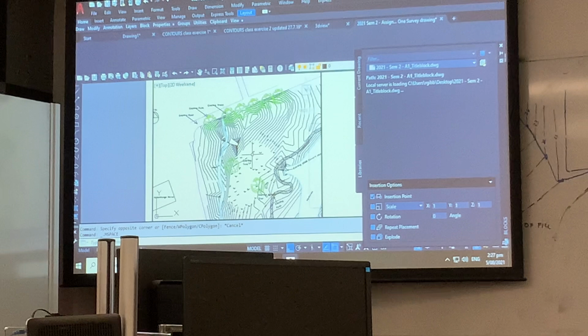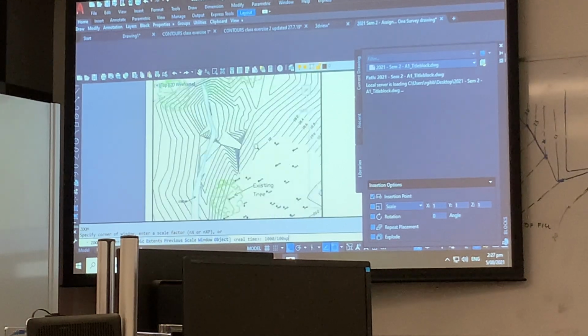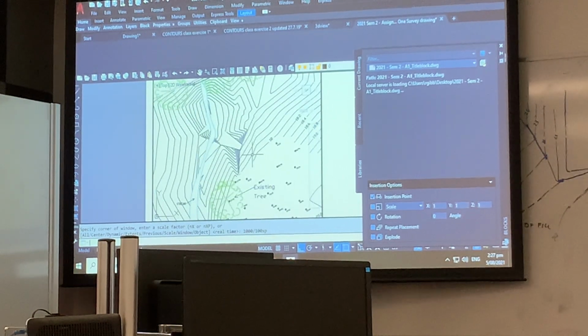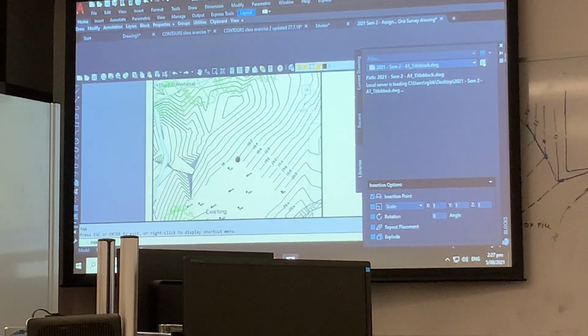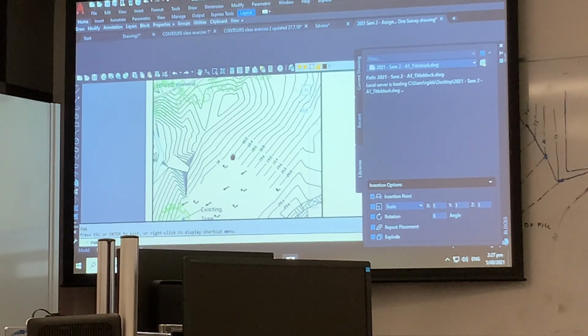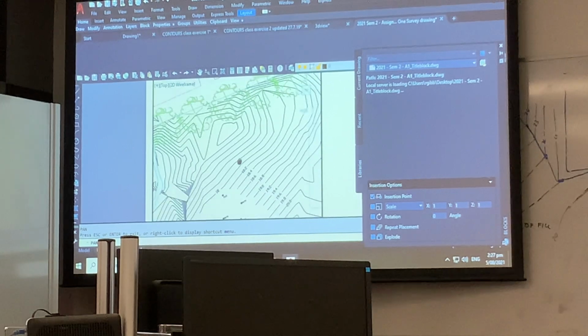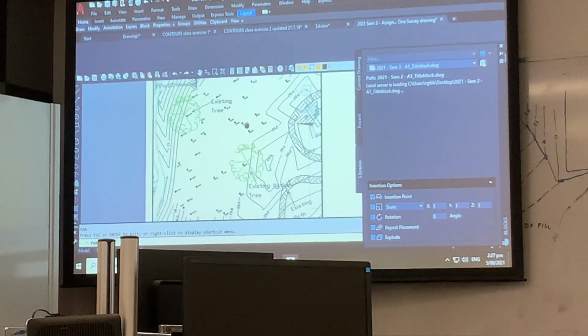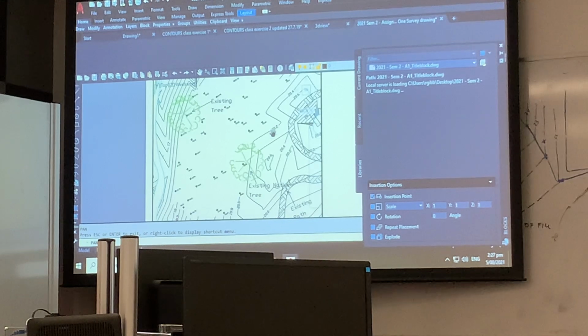The viewport scale: Z, enter, 1000 / 100 XP. And I know a lot of you just went 10 XP because I saw you doing it. It's not a good habit to get into. If you put both those numbers in there, you're always going to get it right. Anyway, where are we? We don't want that bit. We want it from about there to there. The pipe starts there and goes to around here somewhere. So that's perfect. Escape. Double click over there.